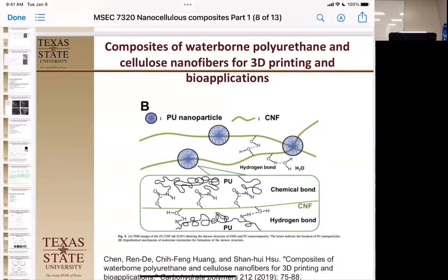But they say because the reactive groups on the polyurethane can react with the hydroxides on the fiber itself, you can get one end and then the other end, and that constrains the entire length in between from being a linear polymer to being a polymer nodule. And then of course, because it has similar intermolecular forces, it will crystallize. So this wasn't necessarily a bad thing or a good thing, but it was still something they did notice.